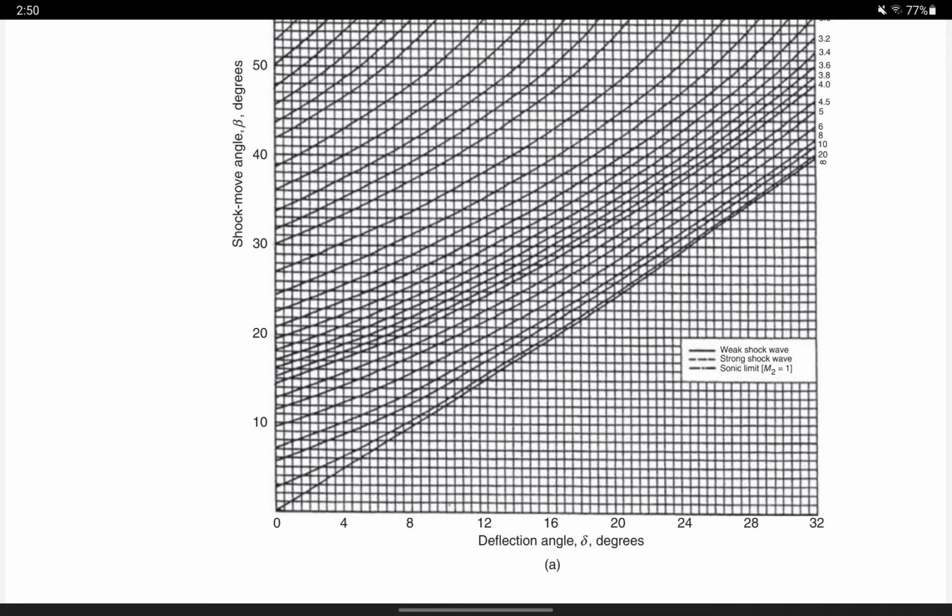As you can see, this is what's going to happen when you're dealing with an oblique shock wave. You will be given one of these angles, and I mean not in quotation, they're literal angles, and the Mach number, and then you come to this table, you determine the other angle, right? Based on that other angle, you can do the calculations to find the normal components. Then you go to the normal shock tables, you read the values, you find the Mach number after the oblique shock waves.